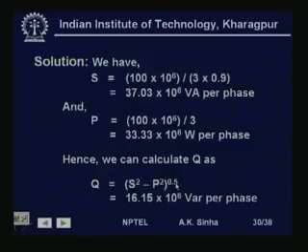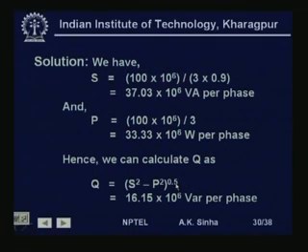Okay. So, this is the example for what we did for the tap changing transformer in today's class. So, now S is equal to 100 MVA, that is 100 megawatt is being transmitted at 0.9 power factor lagging. So, S per phase will be 100 into 10 to the power 6, this is megawatt, divided by 3.